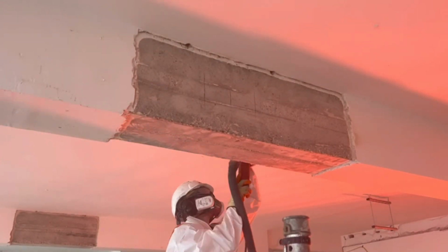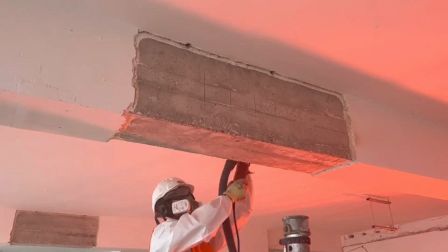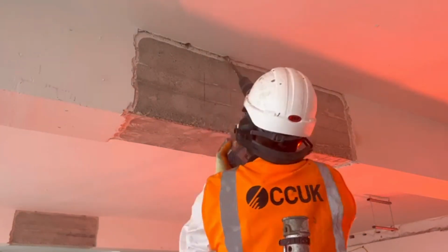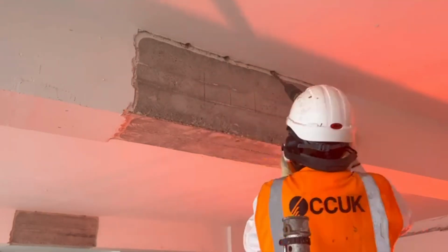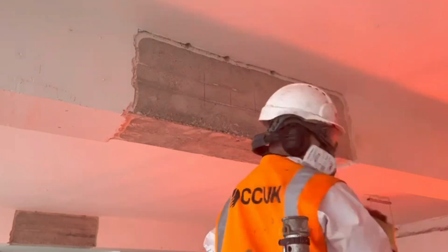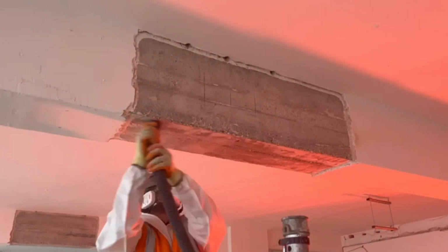This is what he's doing now, though. Yeah, this is a beam strengthening example for shear strengthening, where they're cutting holes through the beam. So in that case, they're using these holes to put the anchors in to get the full effect, as in closed loop. So once that's done, you clean the area, then prime the area using pure epoxy.